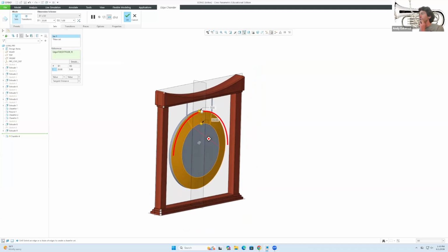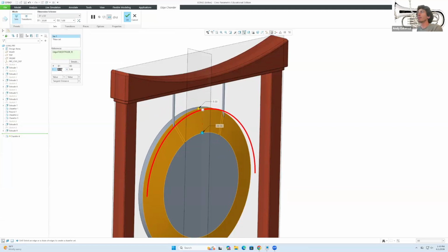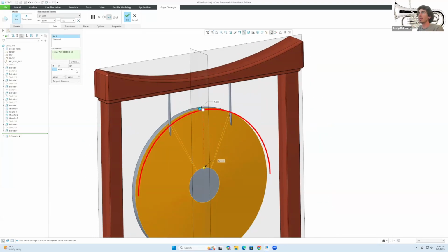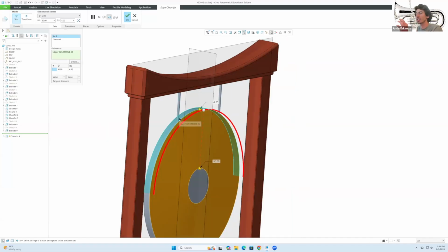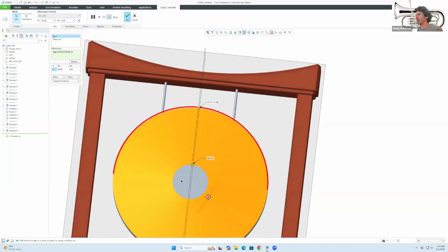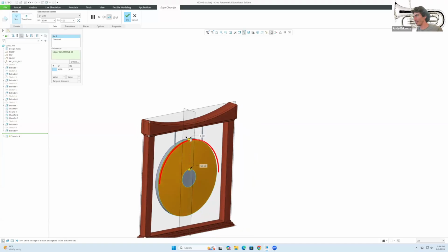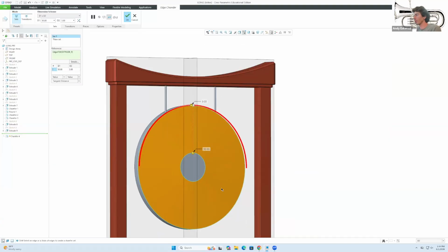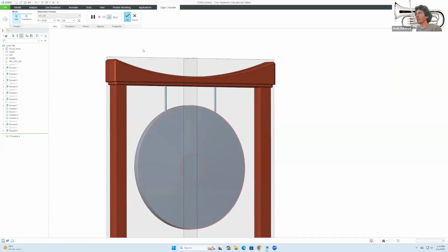You can make chamfers that are different on each side. I'm going to leave that at 20, and then this we can make it like 50. And there, now we're talking. Maybe that might need to be 4, to be honest. There we go. So it's just on the border in there, which is what I want. Good. Because I want that circle to be there, and we're going to color that in a different color in a minute. We're going to make that 3. Good. I think this is fine.